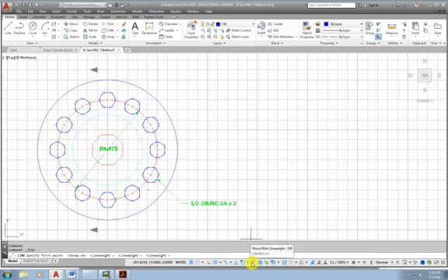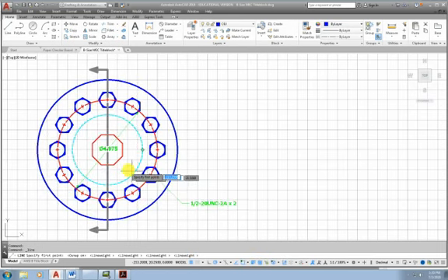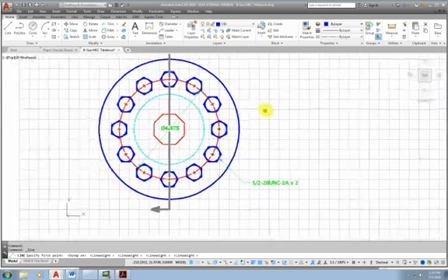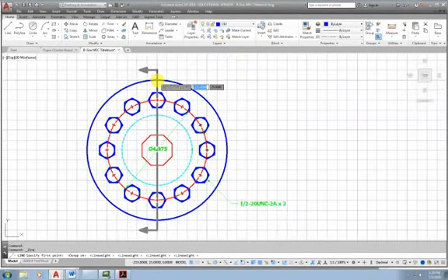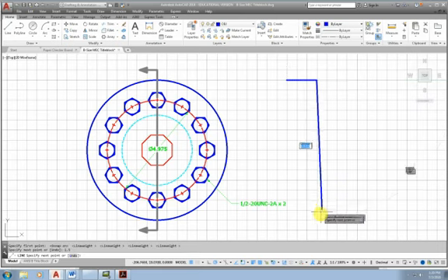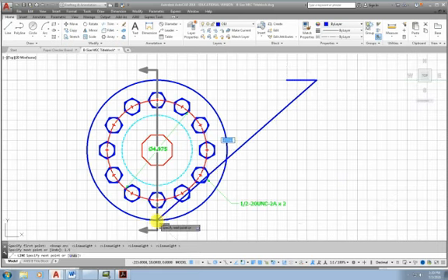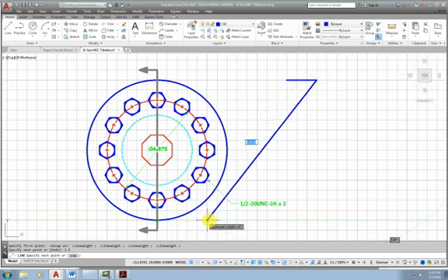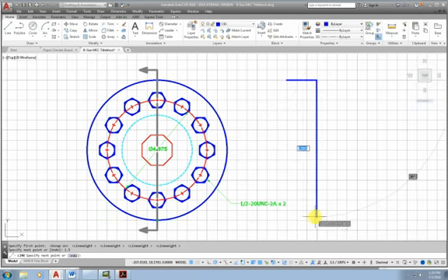If you turn off the line weight, it looks like this. If you turn on the line weight, it looks like this. Much easier to read. So now that I have quadrant enabled, I'll hover, acquire, and you can see since I have my polar snapping on, I can just track that. And then I can go over here and say 1.5, enter. I can come down, hover, acquire, track, bring that back until there we go.